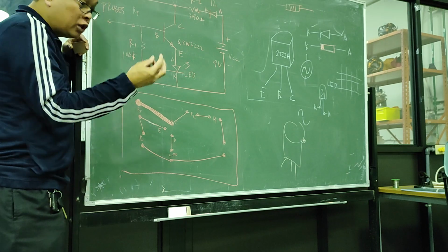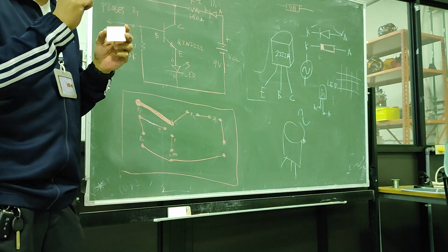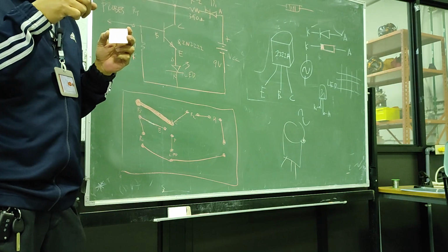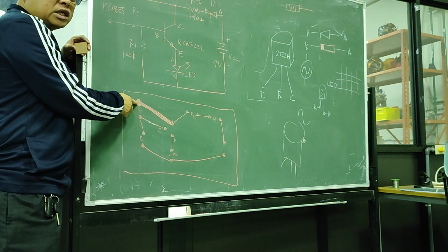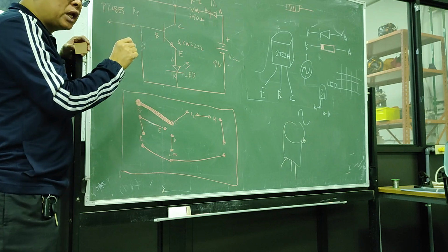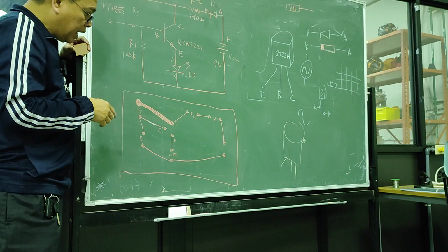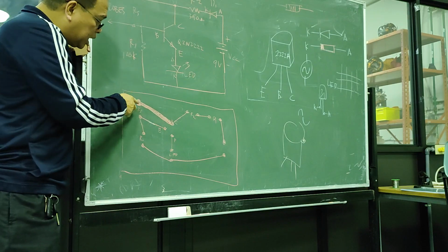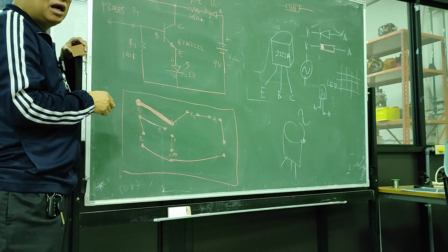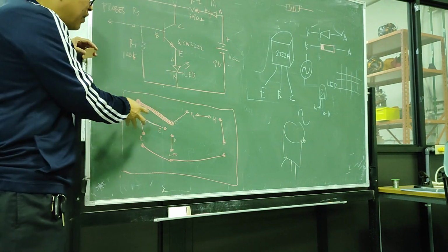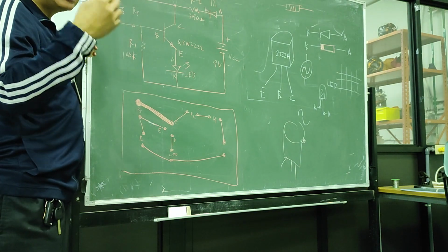The pads are the circular or square portions wherein you will solder your components, the connection points. Later on, you will drill these pads for the component, insert it, and solder it. Another shape is what we call the traces. Again, there are only two shapes you can find in a PCB layout: pads and traces.